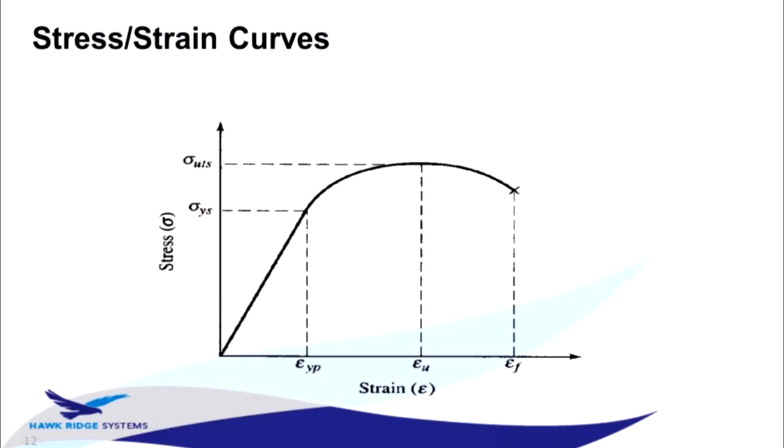The other thing that's worth considering when we look at linear static stress analysis, if you start off by looking at an experimental stress strain curve for something like steel or aluminum, it's going to have something like roughly this shape. The straight line portion below the yield strength, and then some sort of non-linear behavior afterwards. Linear static stress analysis makes this assumption. It assumes that the slope of the stress strain curve matches the linear portion, but it goes from 0 to infinity.